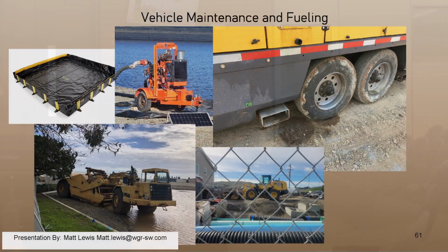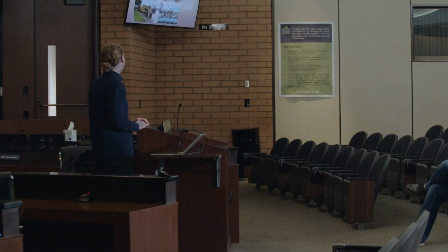This is just a recent site that I have on the down left, where you've got the big soil excavator parked in the middle of a lake. Those things are always leaking hydraulic fluid and everything else. So I had to get those guys to move it to the higher side of the site, which was a fully graveled portion that, if I'm not mistaken, the SWPPP called out as their storage area.